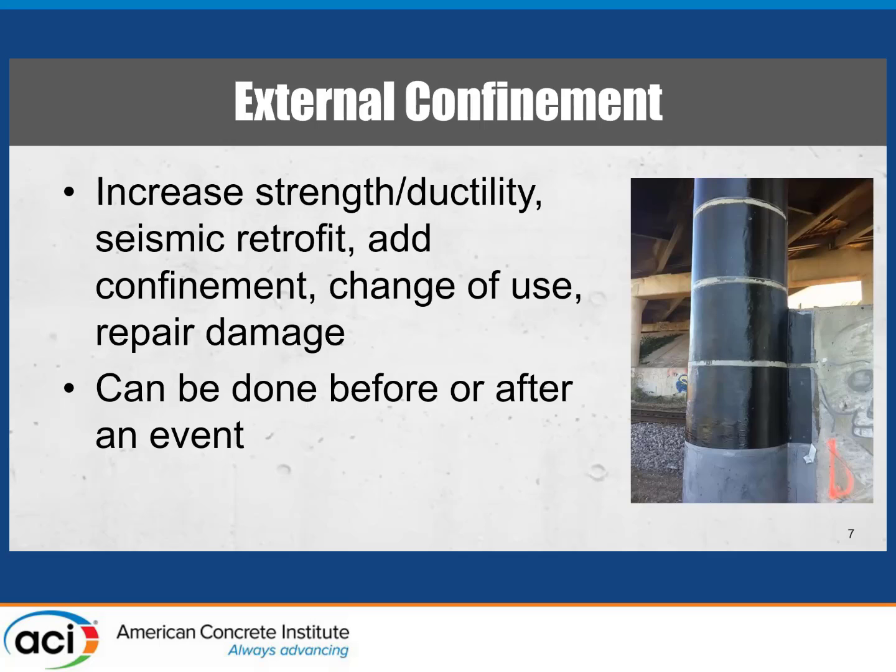You also can repair damage with this. You see it very commonly in marine structures where they use external confinement, typically a fiberglass jacket that's filled with grout, to account for damage to the pilings due to the exposure to the marine environment. And it's also for change of use. Suppose you want to add an additional story or two to a building. Well, one way you might be able to get the capacity out of your columns is to increase the confinement and therefore the capacity of the columns, which would allow you to add the additional load.